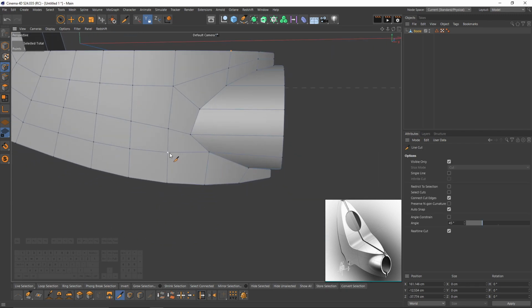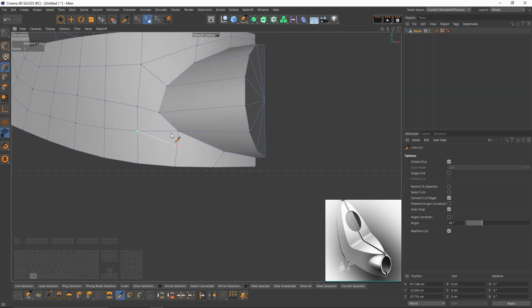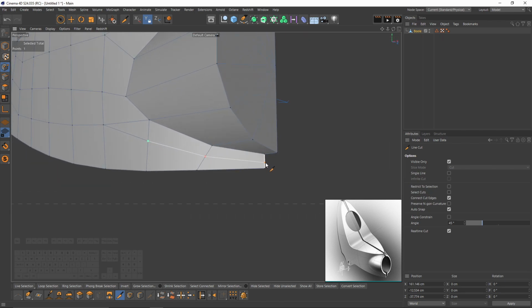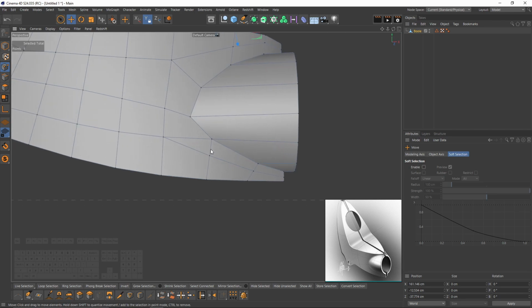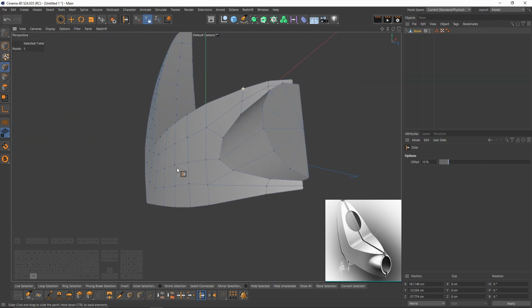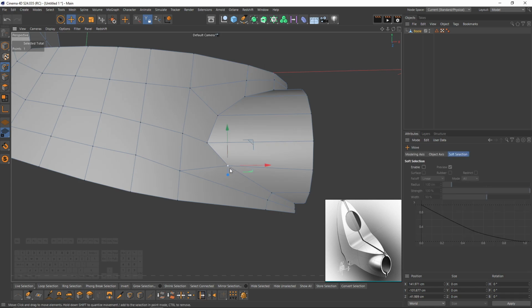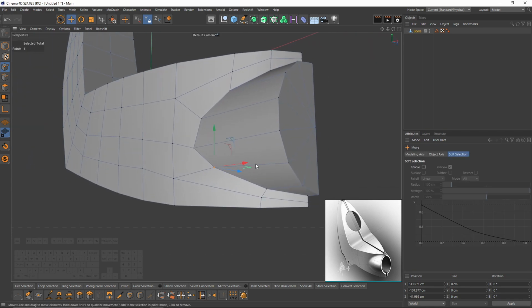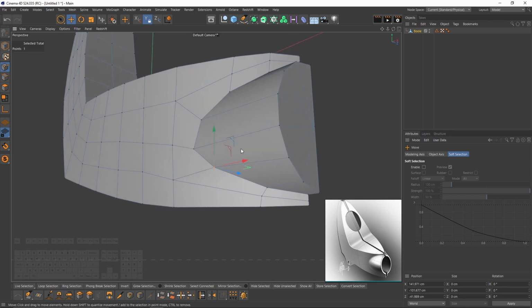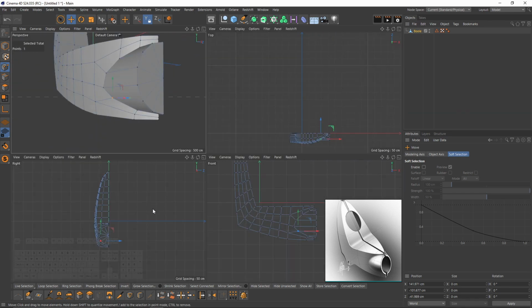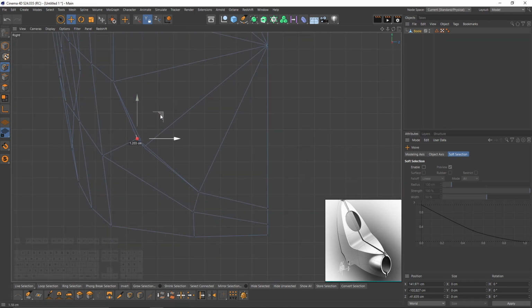We can do something similar for the bottom part. Let's create a new path. Then I'm going to press Ctrl and move that to the next one. This is going to weld it. I think I have moved that point from its original position. As I said, I don't want to break the perfection of the cylinder, so I need to move it back over here. Let's enable snap and snap that.